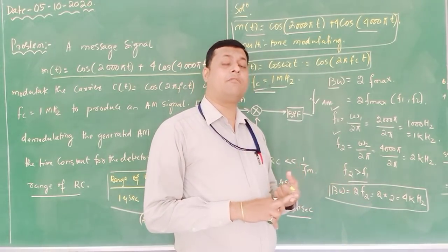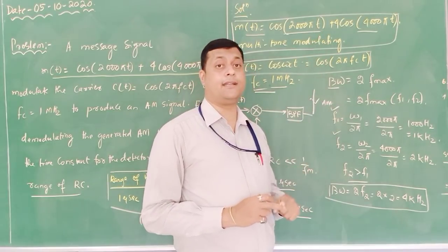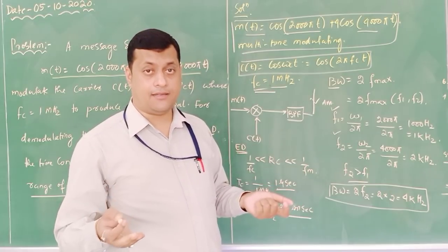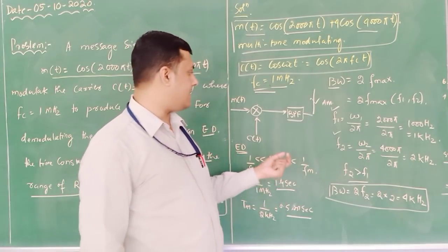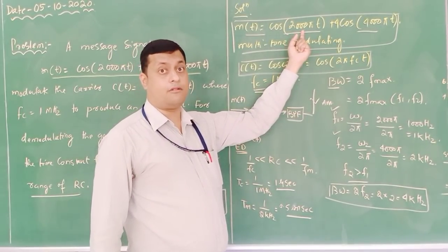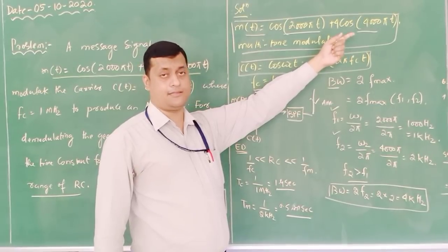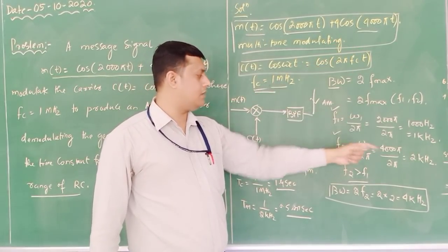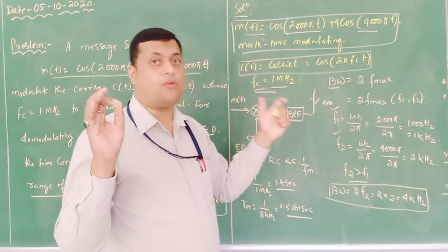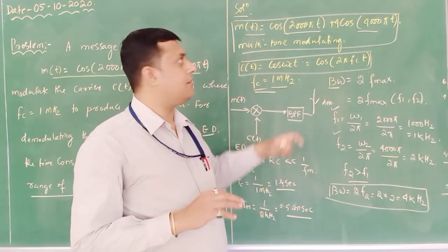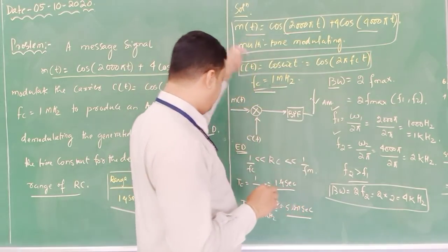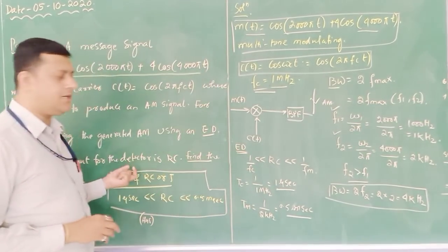Now the maximum frequency available in the modulating signal helps us to decide the envelope detector time constant. So that is Tm, this is Fm. We need not consider this 1 kilohertz, we have to consider 2 kilohertz because the higher frequency, 4000 pi, is given, that is 2 kilohertz. So the maximum frequency is this, so that we can recover both modulating signals, one for this and one for this. Okay, so this is the complete explanation for this particular question.